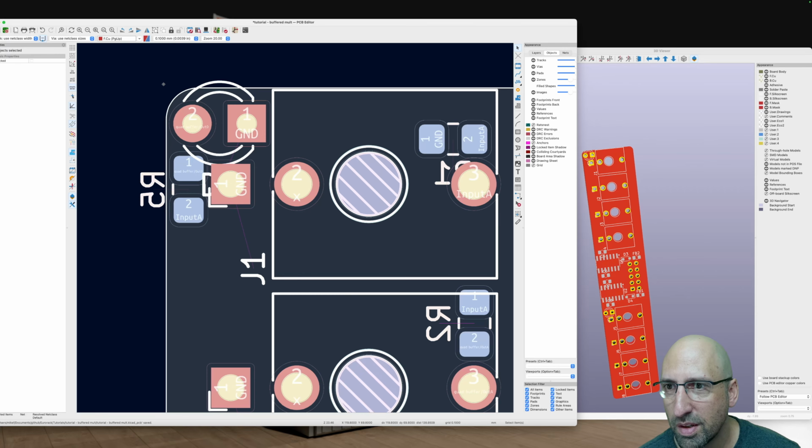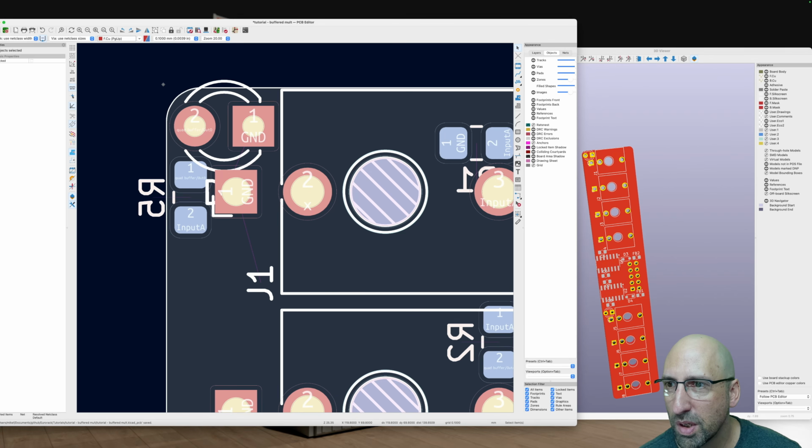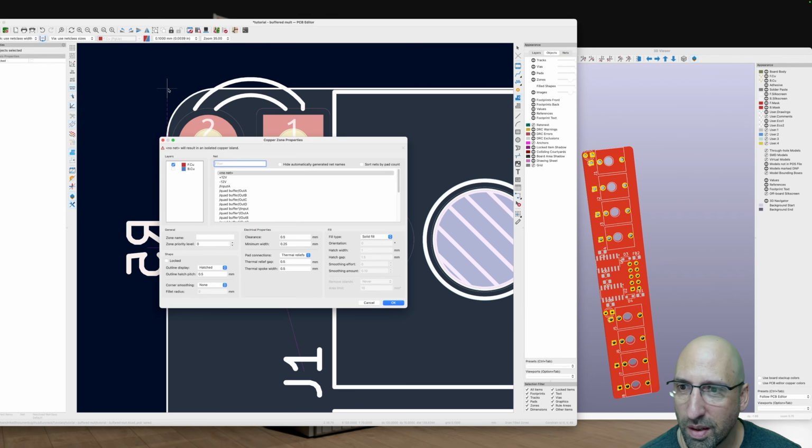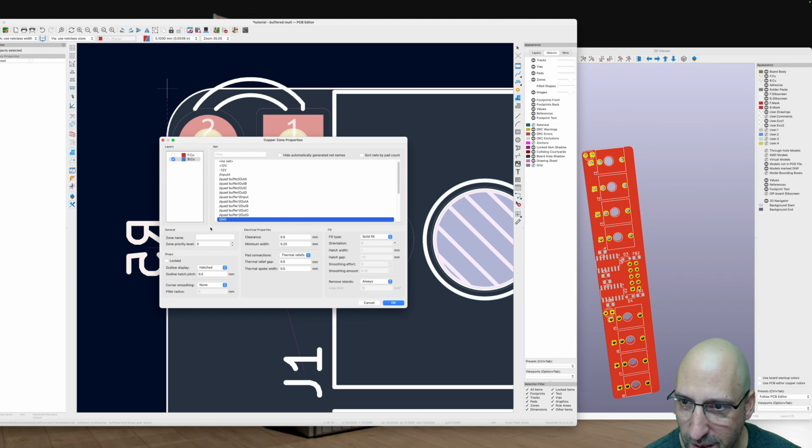Okay. So what I'm wanting to do is draw a zone. That's what we're trying to do. If I hover over this line and go up and get it aligned with this side, about there, I hit the first point. Right, so we want it on the back copper and on the ground plane. Just give it a name if you feel like it. Ground plane.